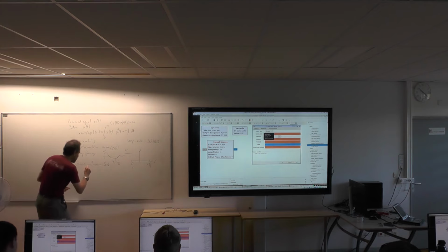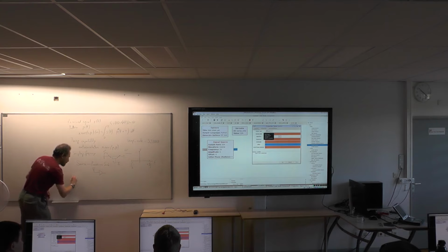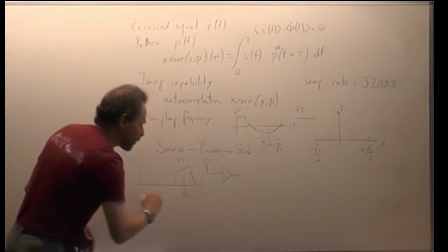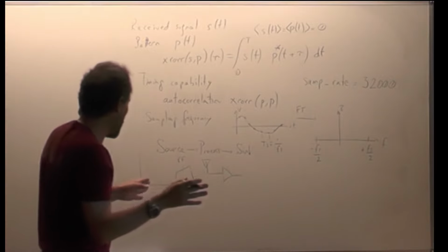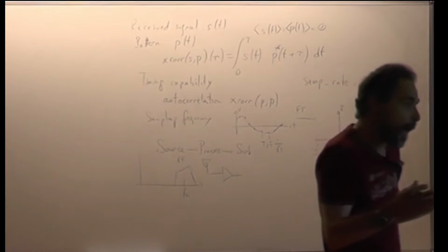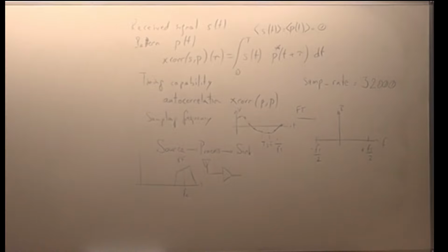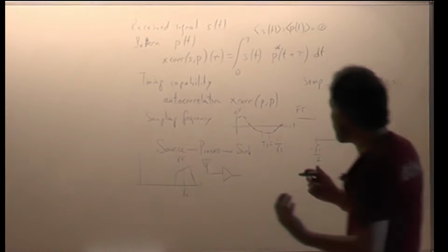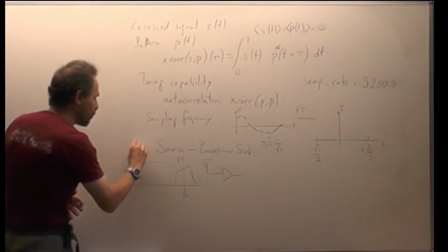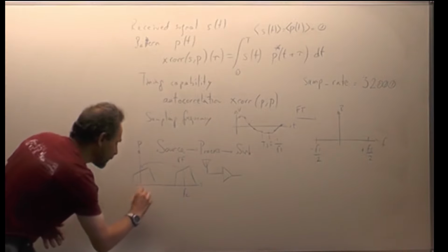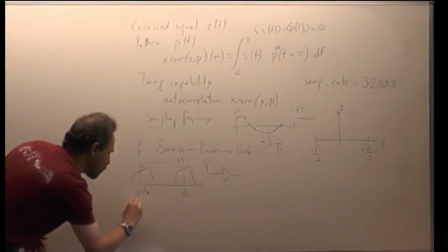When you record the information, you have an antenna. This antenna signal is possibly amplified, and the signal that is coming to your antenna is centered on a radio frequency band, centered, for example, on Fc. This is offset at a radio frequency band for multiplexing the radio frequency spectrum, but when you want to analyze the content, when you want to analyze the modulated signal, you need to bring it to 0 Hertz. So you need to shift the frequency band back to 0 Hertz. And a 0 Hertz centered spectrum is called at baseband.